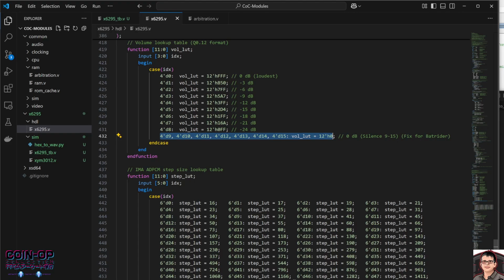When vblank hits, usually there is an interrupt for vblank, and what it does is it signals the system program to start staging things for the next frame. And so you use that information to start processing stuff for the following frame.